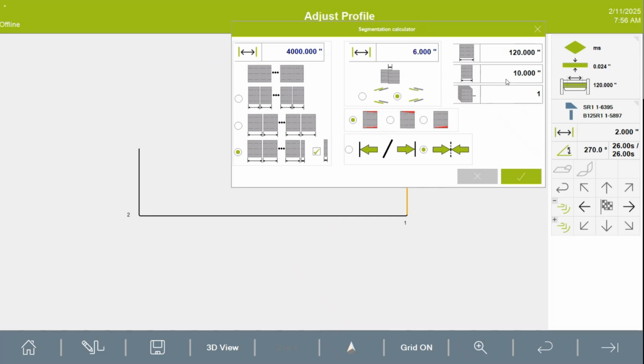I talked to Roger and Elmer at the factory, and the machine really works best when you have a part that's probably 5 feet, 6 feet, and longer. So if you're calculating what we call a splice piece, and it's under 4, 5 feet, maybe 6 feet, then you need to rethink it and go back and just use this method and let them trim that piece. It's not that it can't do it when it's a 4-foot piece or even a 3-foot piece. Depends on the part and how much disparity you're using. You're welcome to try it, but a 10-inch piece, it is not going to do. It won't be able to skew itself enough to make that.